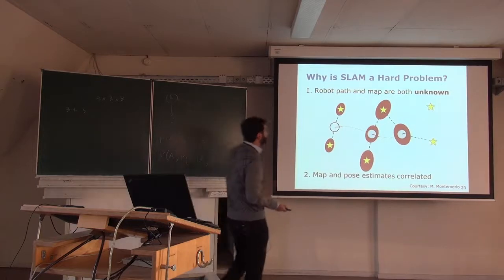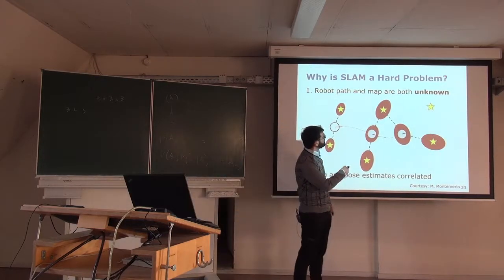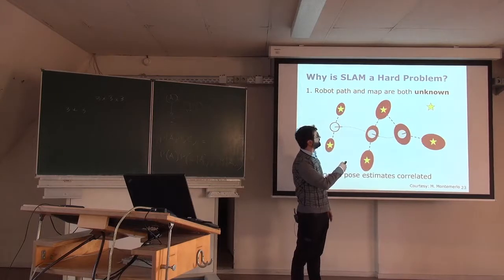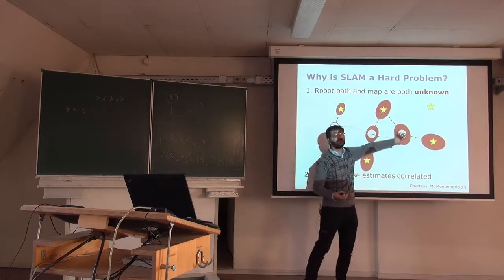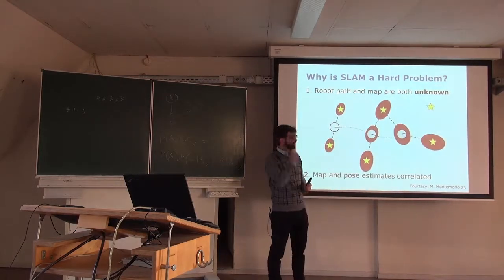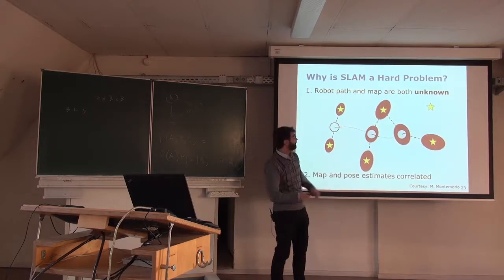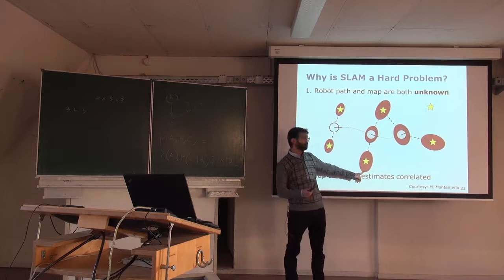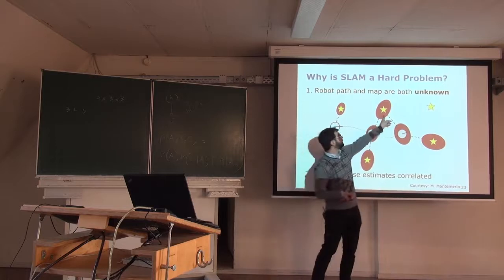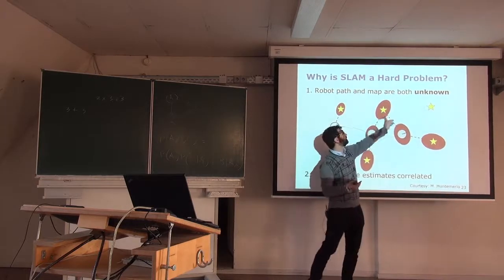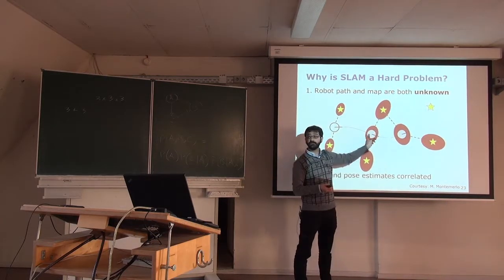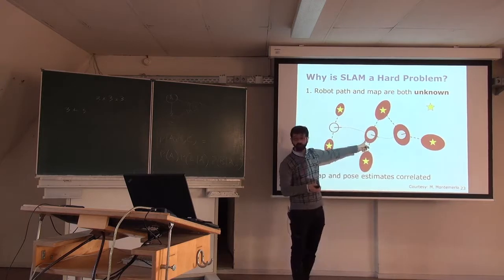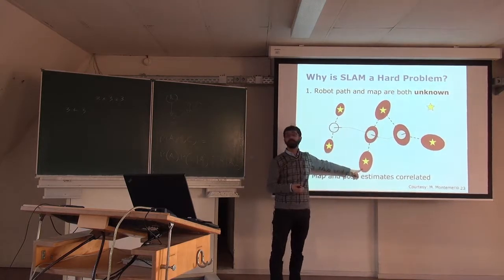You then go on, and what happens is that you get a measurement of the same landmark, and since you're observing the same one, but from different sides, you can somehow shrink this and this and this. So what happens here is that, and that's also a matter of the correlation, the uncertainty of this landmark got also smaller. And that's because everything is connected. By observing this landmark here twice, I know that the uncertainty of this landmark is smaller, okay? But since this uncertainty depends also on that uncertainty, also this uncertainty gets smaller, and therefore also the uncertainty of this landmark gets smaller, okay?